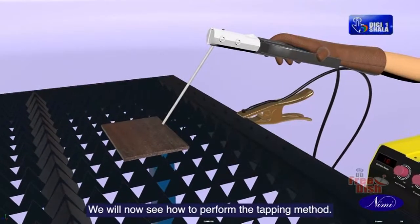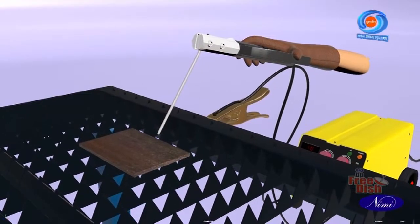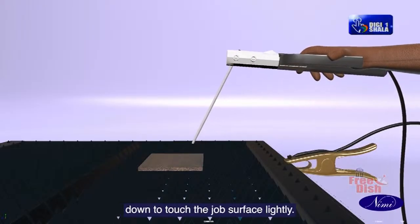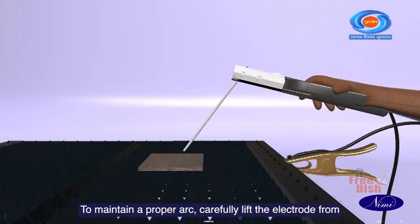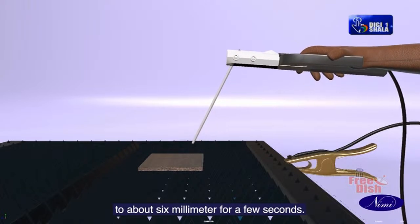We will now see how to perform the tapping method. Strike the arc by moving the electrode down to touch the job surface lightly. To maintain a proper arc, carefully lift the electrode from the surface to about 3 mm and then lower it to about 6 mm for a few seconds.